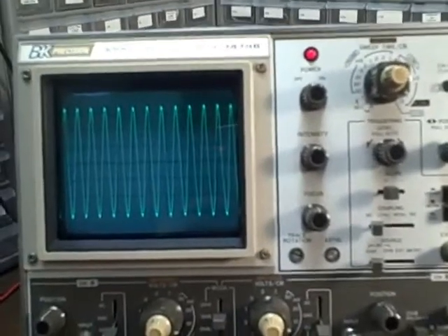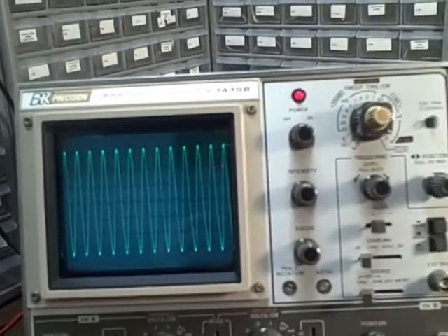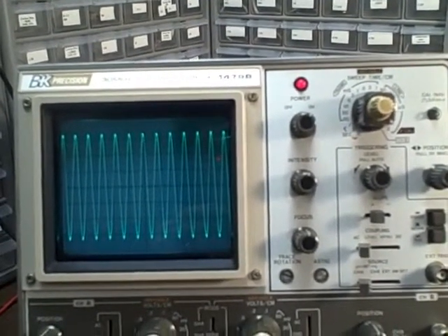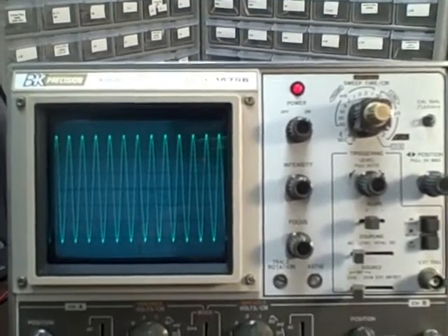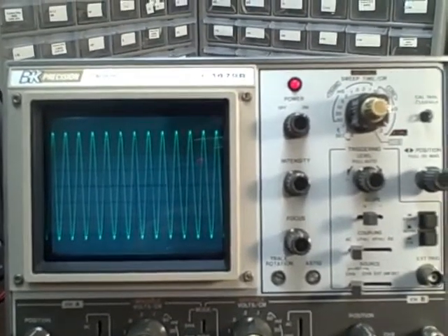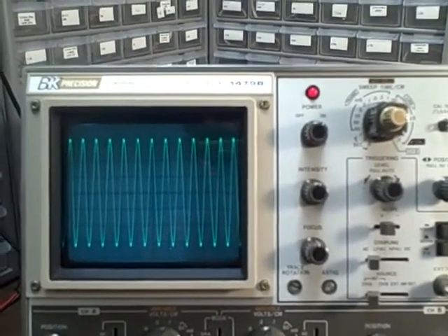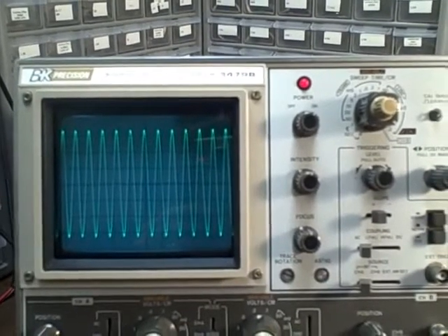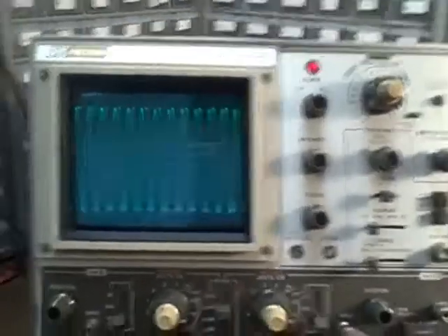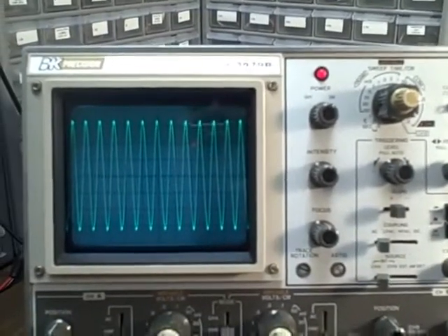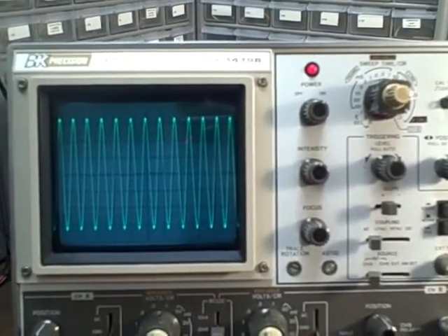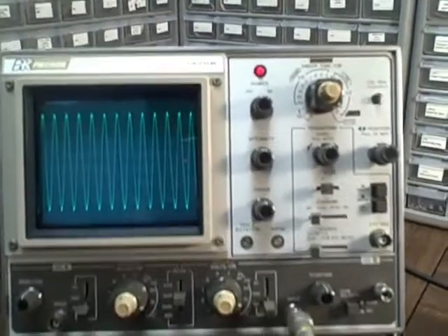We've checked out vertical linearity. We've checked out vertical response. It was accurate. We were able to measure voltages and represent them properly on the graticule. We measured the time base, and it was accurate over maybe 80% of all the ranges that we have available to us. And we saw, because we were using triangle waves, that the linearity was appropriate. And we have now checked the bandwidth and found that the bandwidth was within spec.